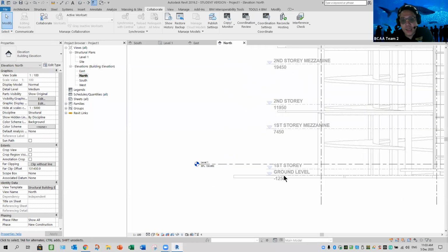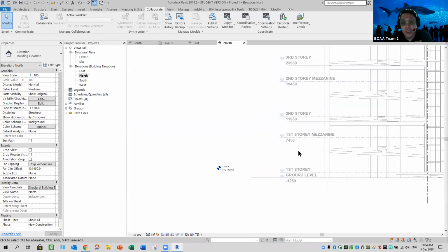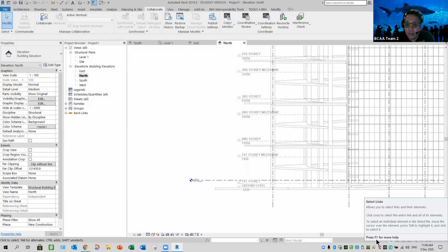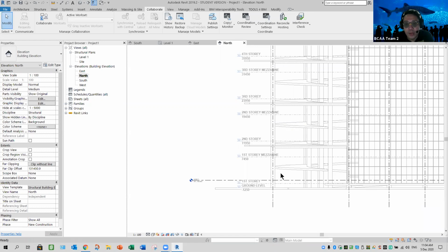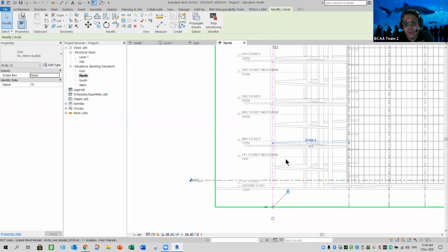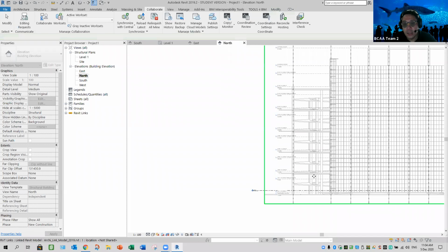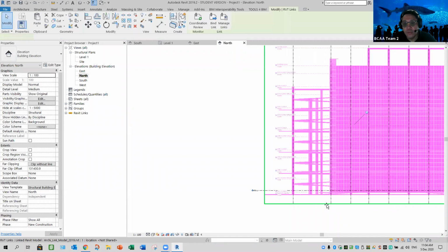Now what we need to do is set this level, first story level, aligned to the first story level. If it doesn't move or you cannot select because of the select link option, which I don't want, I now uncheck it. I should be able to highlight. And can I move? Oops, not my grid, definitely. Is the model here? Can I move? Cannot. It has been pinned.